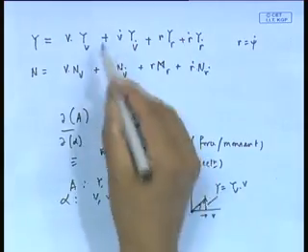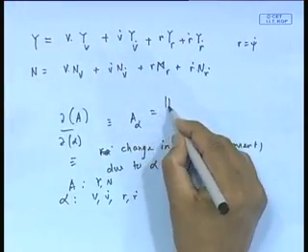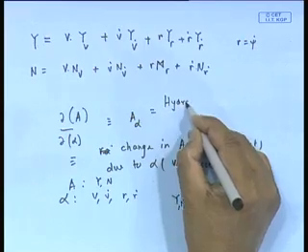Now, how much it is we do not know, but this becomes a characteristic of the hull. That means I am saying, let me find out for my given hull by some means how much will be the y per unit v, then I will calculate and keep it with me. So that becomes, just like our BMT, KMT etc., a hydrodynamic property of the hull. These terms are called hydrodynamic derivatives.